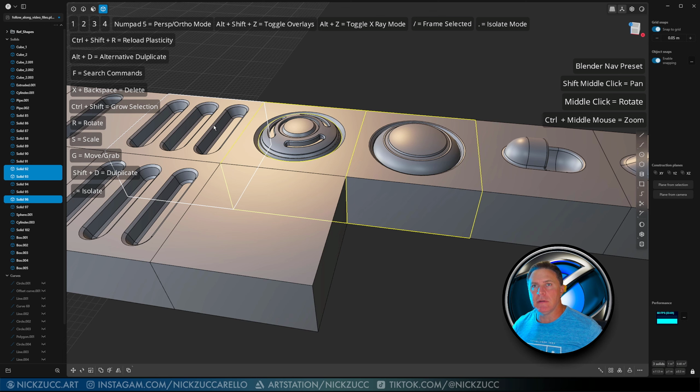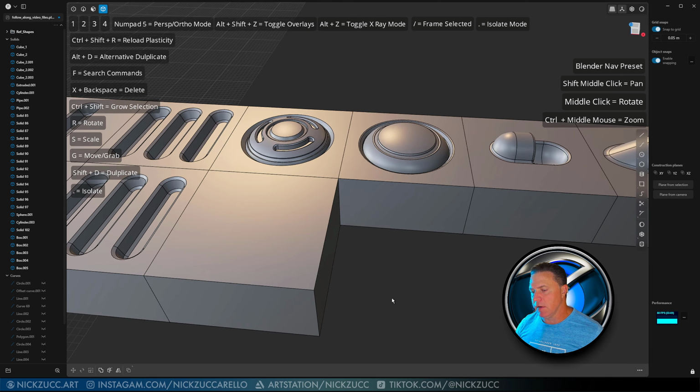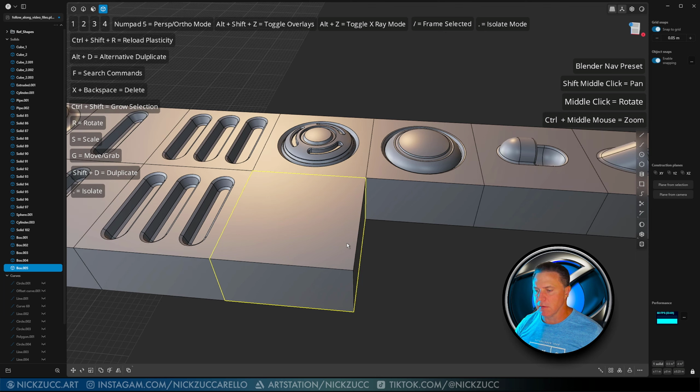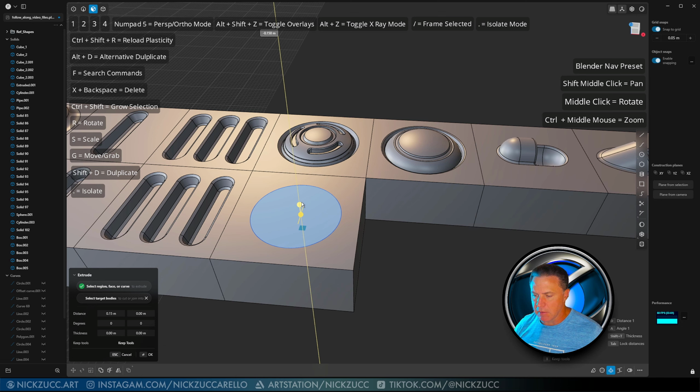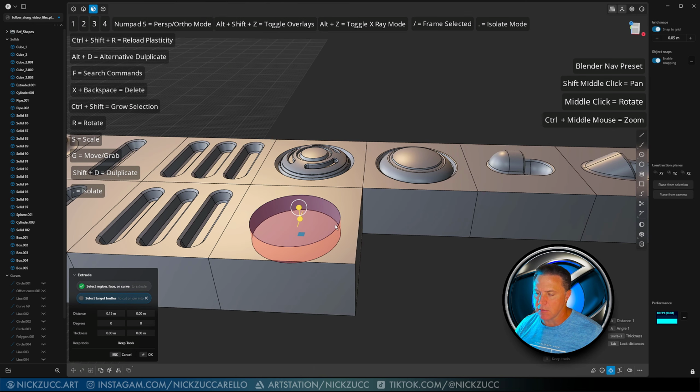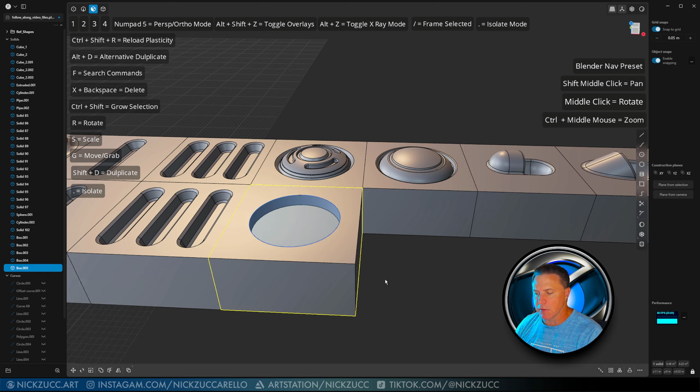All right, let's go ahead and take a look at the two shapes that we've got here. So for this, I already got the block going. I'm just going to use this center circle, so you can click and drag out here from the top. I'm going to go ahead and snap to the center here, just like this, and then snap to this area. So for this, I'm just going to tap 3, and I'm going to push down like that. And to do a difference, we can tap W and select this body, so we can just cut directly into the body like that. We'll go ahead and right click to confirm.